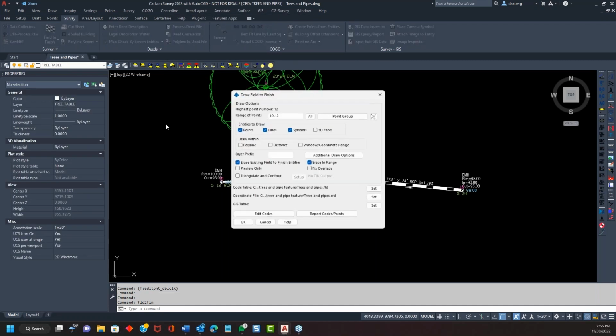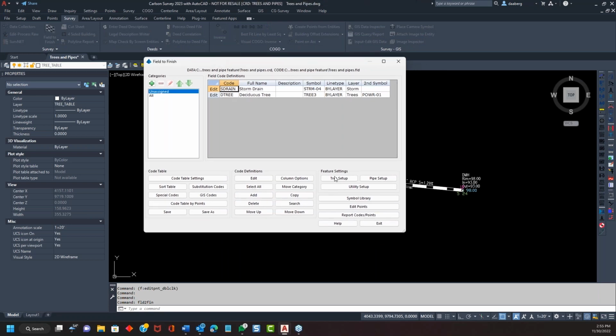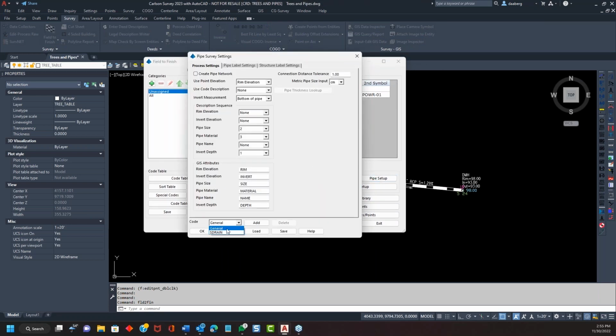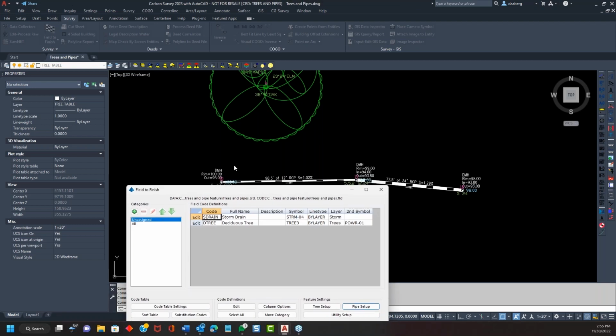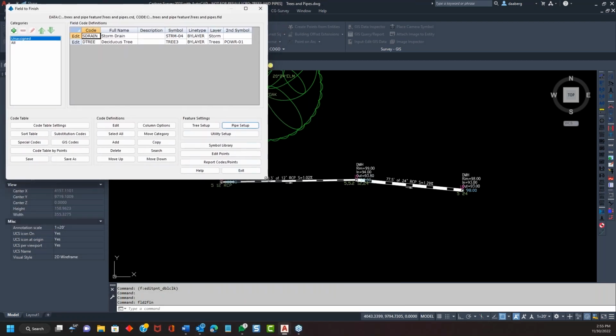And this is another thing that I really like to take advantage of, but you have to have the Carlson hydrology module to make any good use out of it. You can actually create a pipe network, and it creates a .sew file that works with the hydrology network, and then I'll get a sewer network created, and I can plot a profile of the sewer as well. So I use that religiously for as-built because once I get all the information, that's usually what I have to show on an as-built. It's not just the plan view. I've got to show a profile of the final pipe.